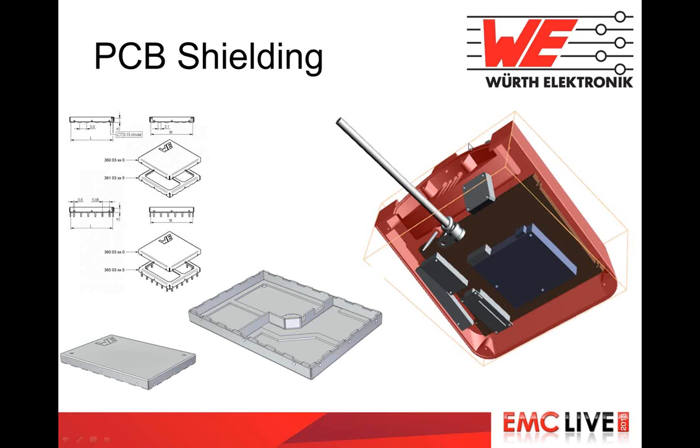The challenge here is that when you buy a PCB shield, you have to connect it to your PCB, but your PCB shield has only 5 sides. A complete shield needs 6 sides. Naturally, the sixth side you have to provide with your PCB. That means you should have a really good ground plane under the PCB shield and connect it properly, again minimizing the number of apertures that you are leaving. This is the critical point. The shield can be very good, but if it's not placed correctly or the PCB is not designed for the PCB shield, it will not work at all.